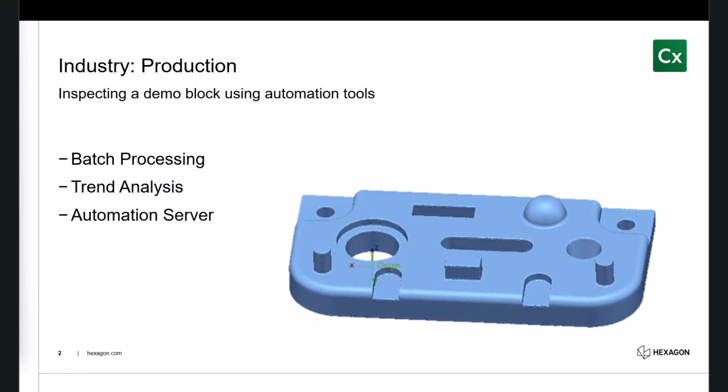We've covered that already. I'm going to be using just a pre-baked inspection report that I've already made. With that, we then start the batch process tool, drag and drop our scan datas into that, tell it what we want it to export, a PDF, an XML, or CSV, whatever you'd like, and then hit go, and it's just going to do it all for us.